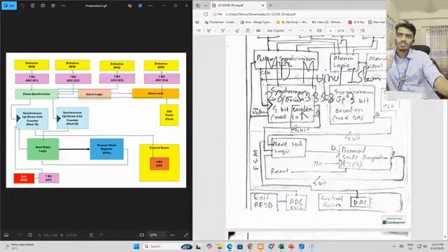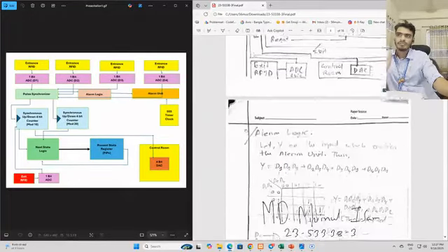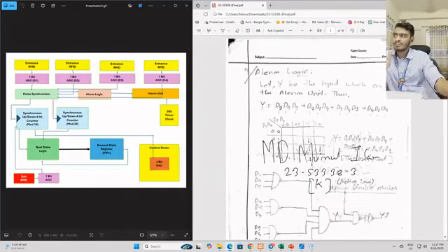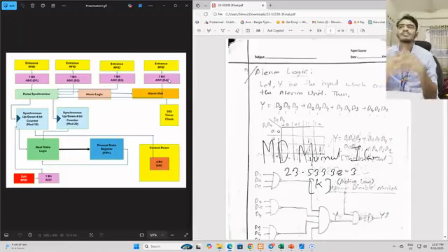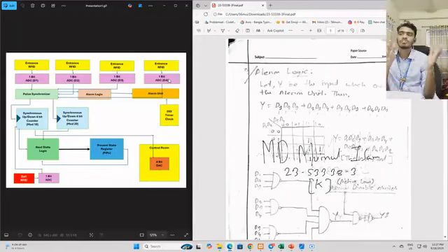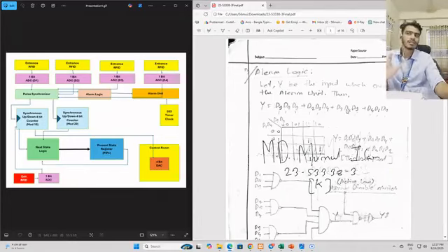We have not explained the alarm logic here yet, right? So let's go through the alarm logic. Remember, I have D1, D2, D3 and D4 as outputs of the entrances. So there are 4 entrances. If 3 passengers cross the yellow line simultaneously, it should trigger the alarm. If we calculate the combinations of 3 from 4, 4C3, it is actually 4. So these are all 4 combinations. If D1, D2, D3 go high at a time, or D2, D3, D4, or D3, D4, D1, or D4, D1, D2 go high at a time,